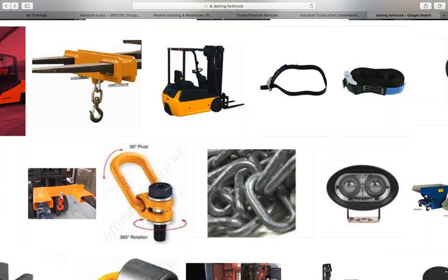And then, of course, keep in mind that when we use taglines, one of the main considerations that we want to make with taglines is that we use preferably non-conductive taglines. And folks, this is for any tag line, whether we use a crane or a forklift. Don't have any knots in it. Don't put any eyes in it or loops or anything. Just one straight line and long enough for employees to safely operate with it or try to help assist to balance the load, but not so long that it may become a trip hazard or get them wrapped up and drag them or pull them up.